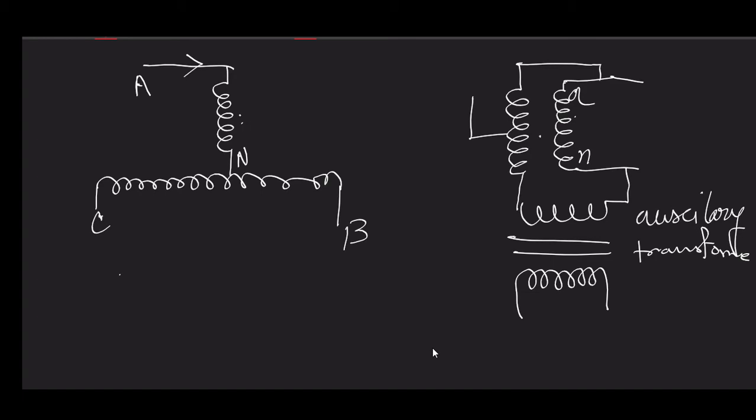While you keep this side unused, if this L is sufficiently large, then for light load you can always get almost a 90-degree phase displacement between these two windings. Whatever voltages or currents you get, there will be a phase shift.